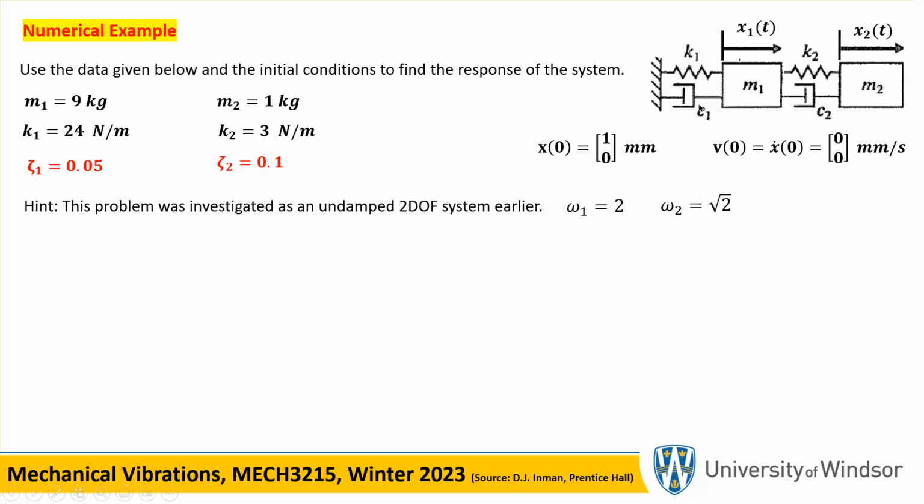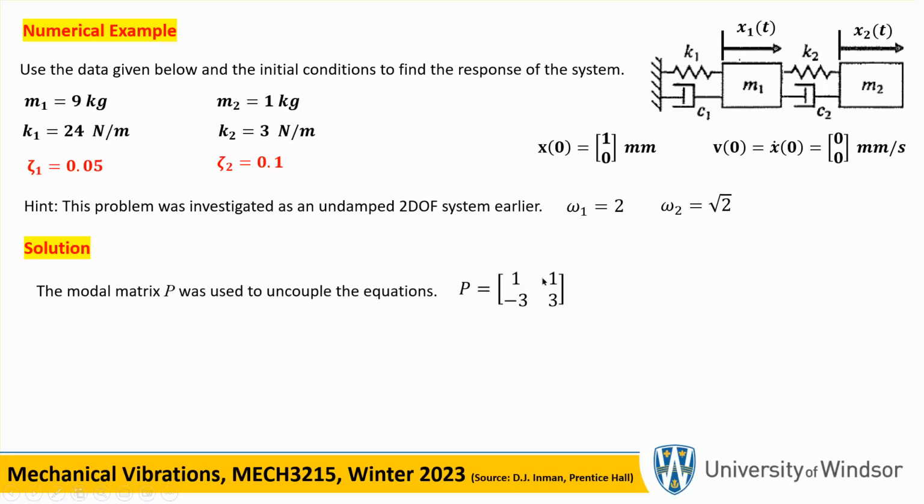So suppose that the first mass has a damping ratio of 0.05, and the second one a damping ratio of 0.1. Some initial conditions are also given to you. The first thing is to get the decoupled modal equations, and that is done through the stuff here. These were the frequencies that we had to find, and since we have already done this problem, I just took them. And these are the mode shapes, which you have to find patiently one by one.